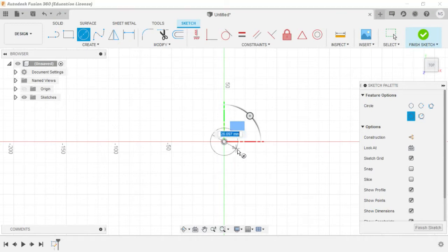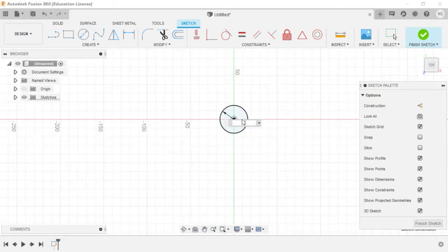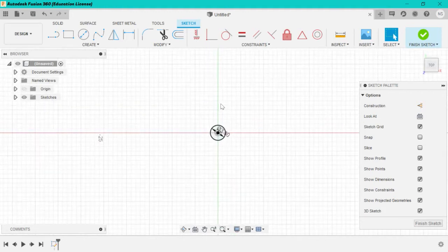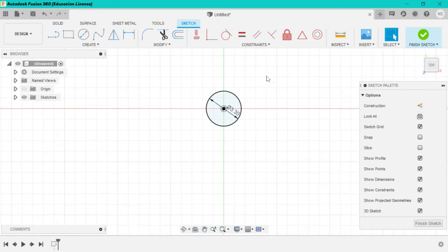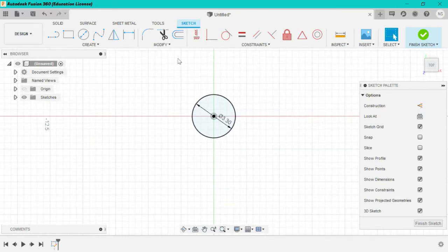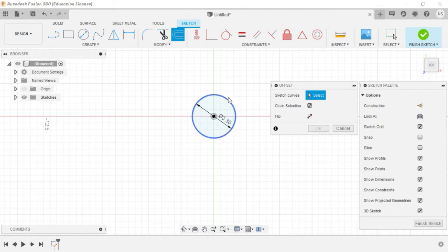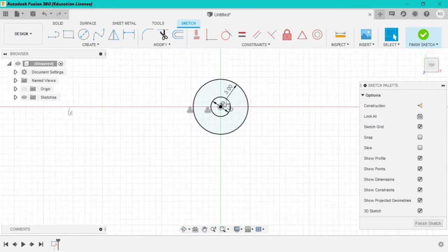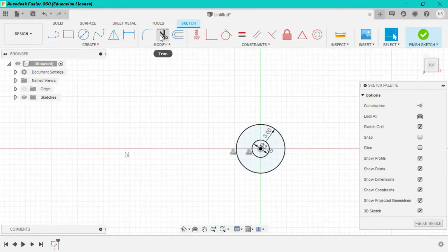Let's create a dimensioned circle. Okay, here I am giving the diameter of the axle as 3.2 mm. It is okay. 32 would mean 3 centimeters, and there is no axle with 3 centimeters in our range of DC motors. Okay, let's create an offset with a thickness of 3 mm. 3 is enough, I think. And I have to create another offset.